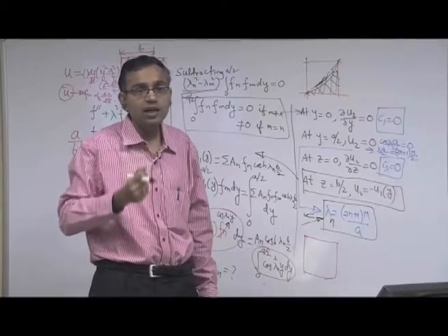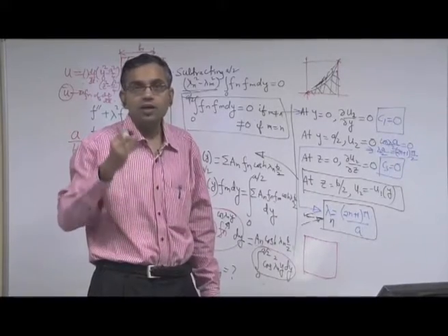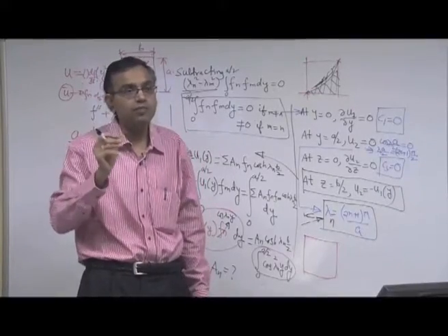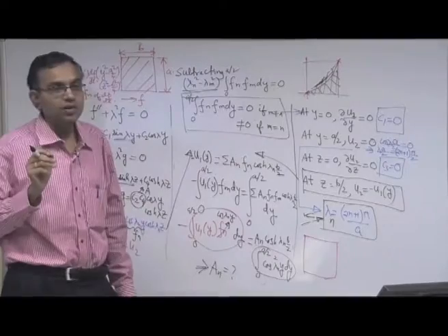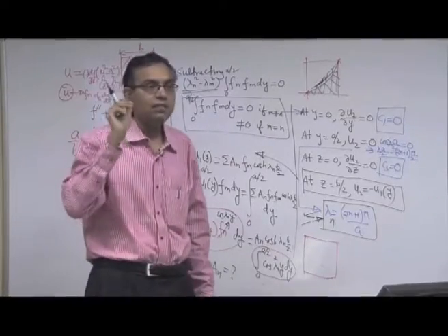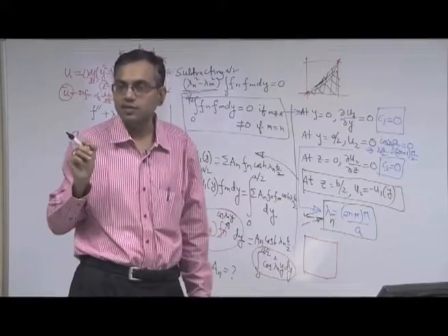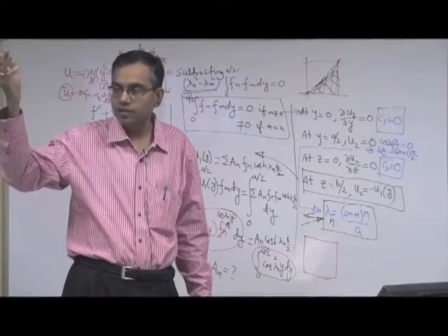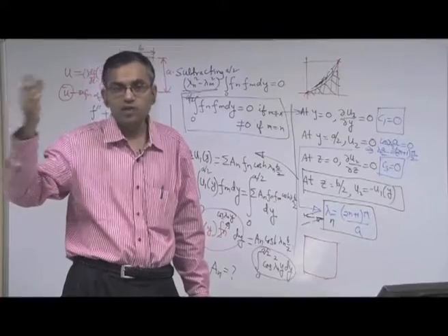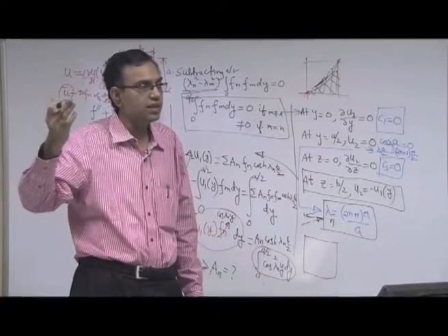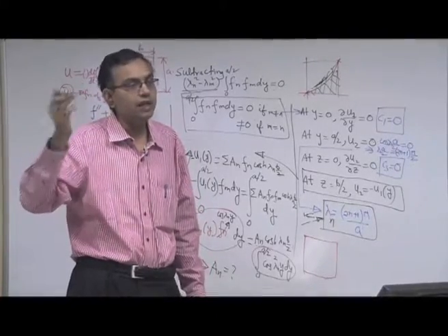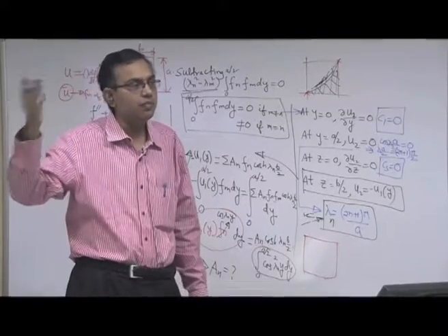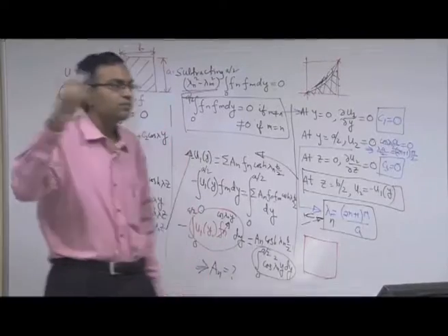But you will see that as an engineer our objective of interest many times is the velocity profile, but more commonly to calculate the frictional loss or the wall shear stress. So that is given by some integral of the velocity profile, not the velocity profile directly. So errors in the velocity profile do not show up that much, provided that errors in the integrals of the velocity profile are not very high.